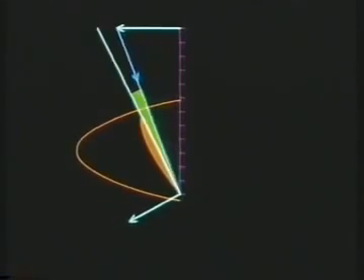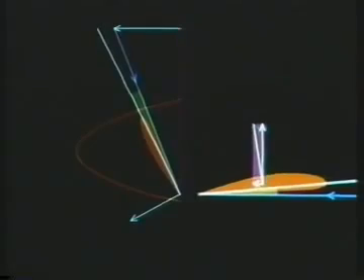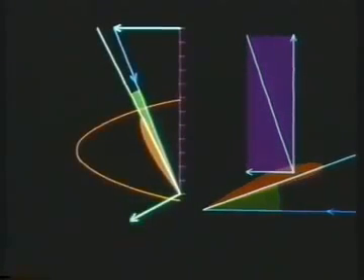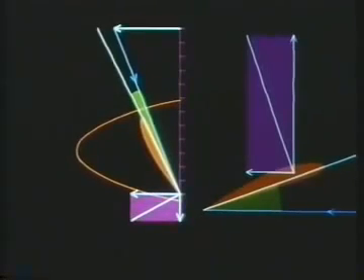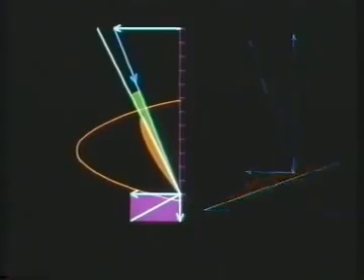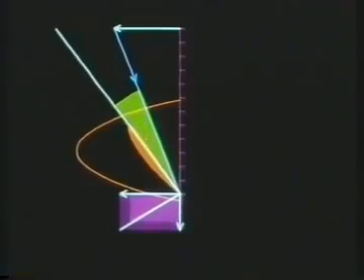Remember that the total reaction produced by a wing aerofoil can be resolved in terms of lift and drag, and that the penalty for increased lift is increased drag. With a propeller, the total reaction is resolved as thrust, the force needed to overcome the drag of the airframe, and the propeller drag, or torque, which balances the power output of the engine. The penalty for increased thrust is increased torque.